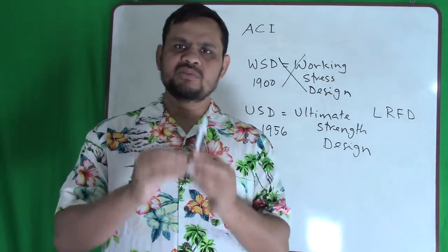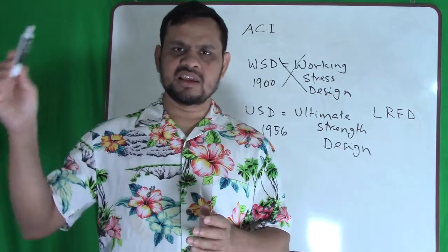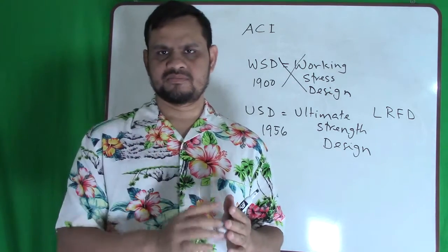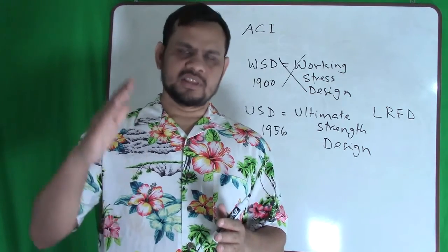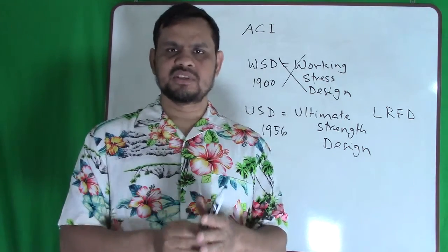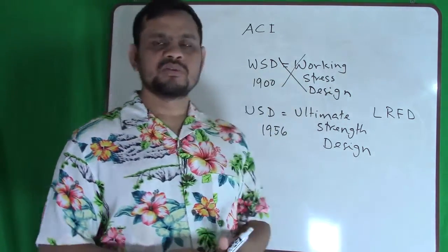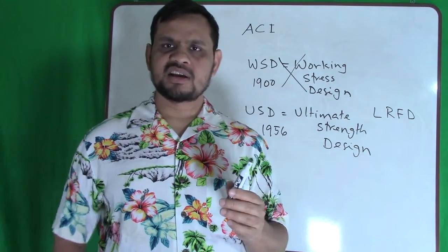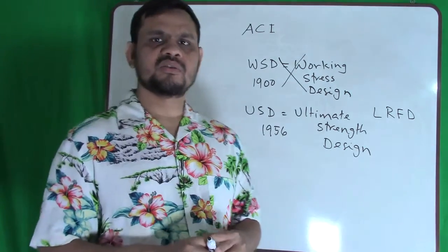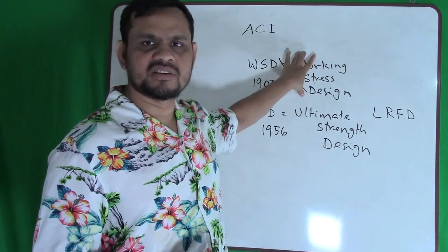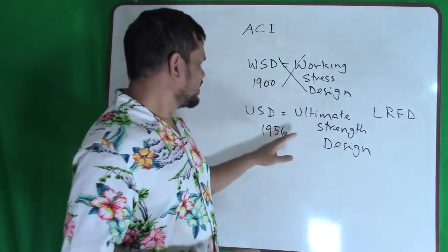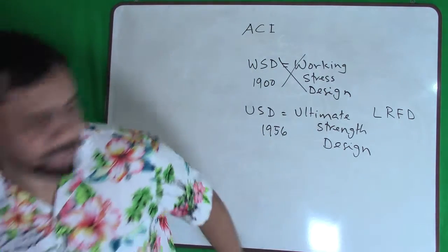Now we can use this cable anywhere in a structure where the stress is 10 or less. That is this method: whatever the capacity of the material, we divide by a factor. So it is not economical, because we do not use the full strength of the material.